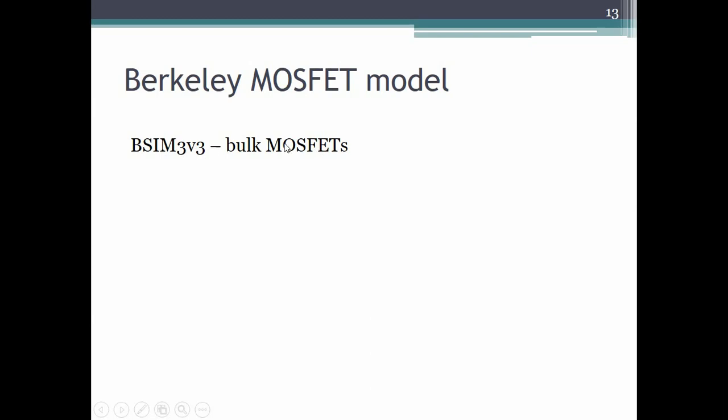Now, MOSFETs are also of many different types. There is the silicon on insulator, and then there is a double gate, and then there is a FinFET, and all of these have to have their own models. This course is about bulk MOSFETs, and so we will be using the BSIM 3v3 model for the bulk MOSFET for all our SPICE based designs. And the version of SPICE we will be using, called LTSpice, has this model incorporated in it. We will not have to